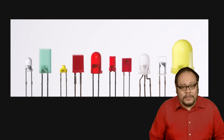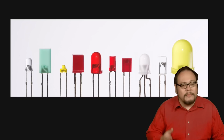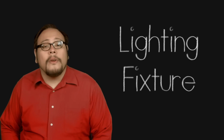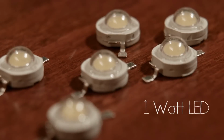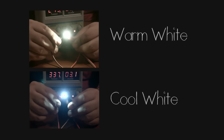LEDs come in a variety of shapes, sizes, and power draws for different applications. The first application for filmmakers you might think of would be as a light. For this, you'll want to turn to the high power LEDs. These are LEDs rated for 1 watt or above. These little button LEDs, which are available both as warm and cool white, pull 3.3 volts but draw 300 milliamps or so. Multiply volts times amps and we get watts, so it's about 1 watt.